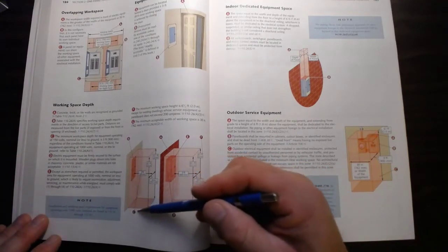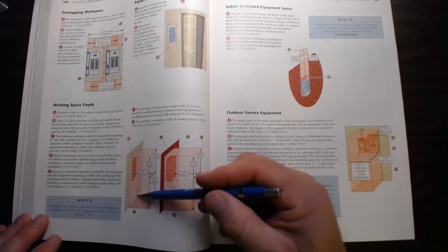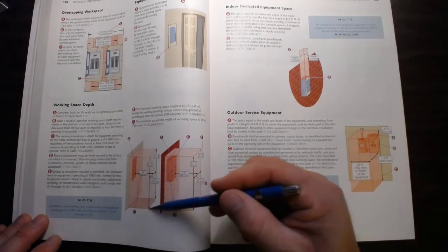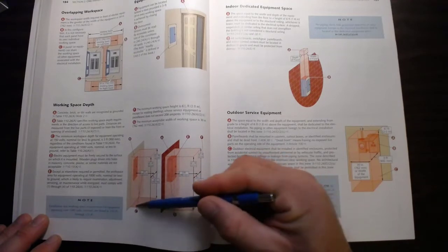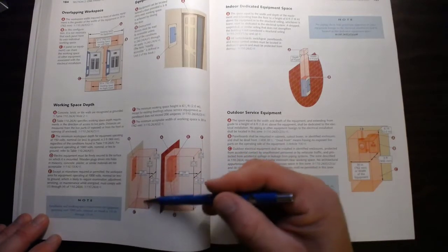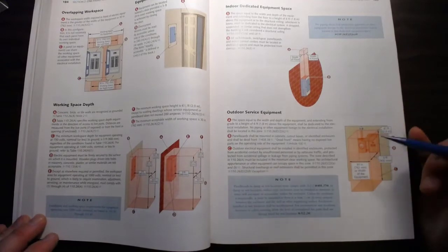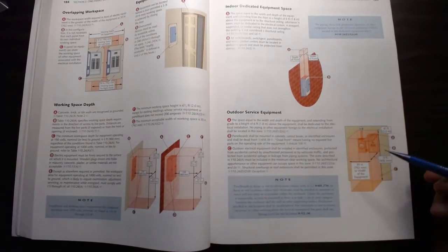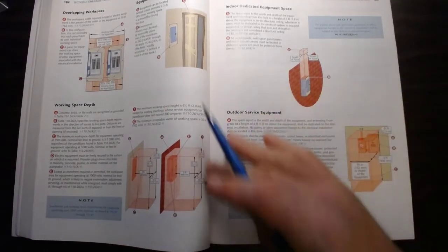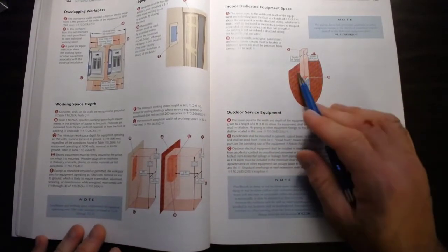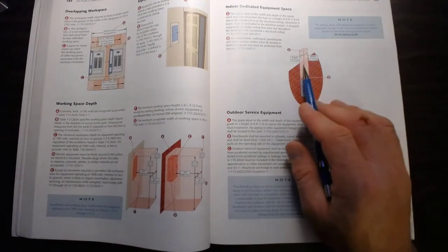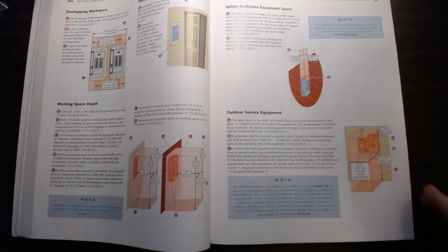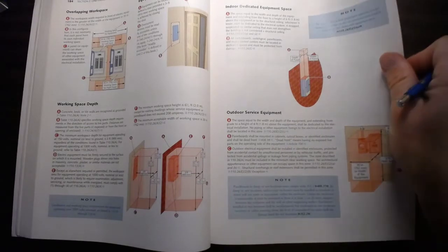The biggest problem in commercial areas is they put stuff right in front of these panels. So a lot of companies have put down on the ground, marked it with yellow tape, and said no storage. But we still inevitably end up finding things in front of panels. So these depths and dedicated working spaces are important. This dedicated working space allows us to run conduit out of that panel, so we don't want to put anything else in the way.